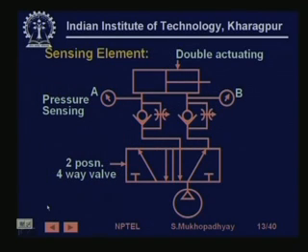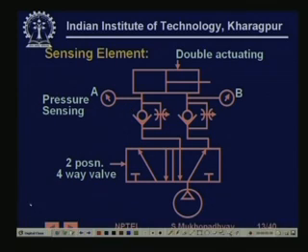So, exactly that is shown. You see that you are sensing this pressure A and pressure B, and then you have to use an appropriate logic to actually drive this valve, so that a certain amount of force is developed.